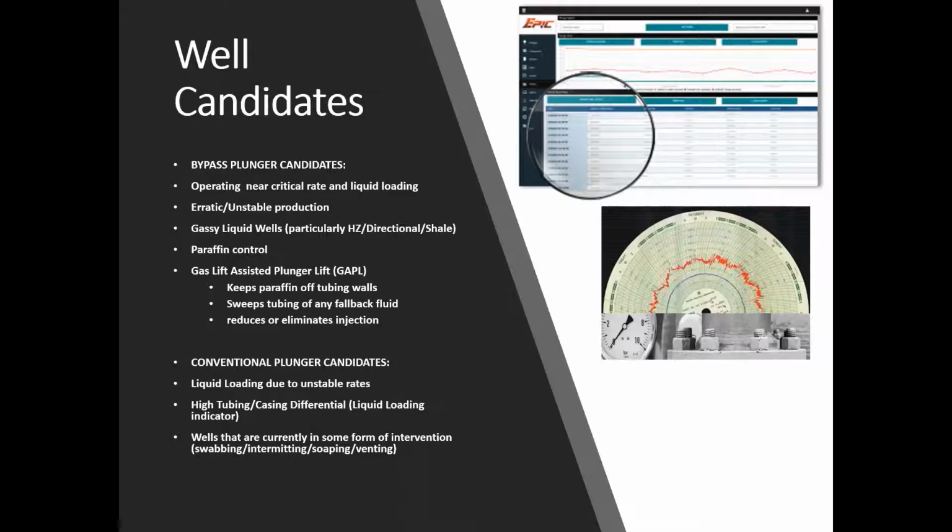Conventional plunger candidates for liquid loading due to unstable rates, high tubing and casing differential, and a liquid loading indicator. Wells that are currently in some form of intervention: swabbing, intermitting, soaping, or venting.